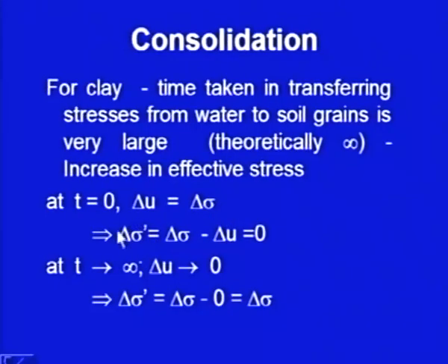That means, the incremental effective stress, just now I have discussed the effective stress concept. Total stress is equal to effective stress plus pore water pressure, and the effective stress is equal to total stress minus pore water pressure. So, here we are taking the incremental values. So, incremental effective stress will be equal to incremental total stress minus incremental pore water pressure. So, at time t equal to 0, just after the application of the surcharge, the increase in effective stress will be 0.